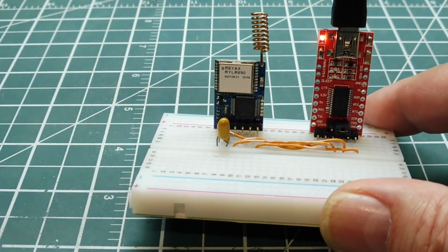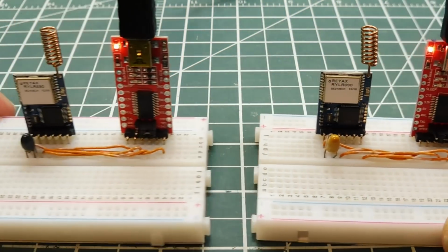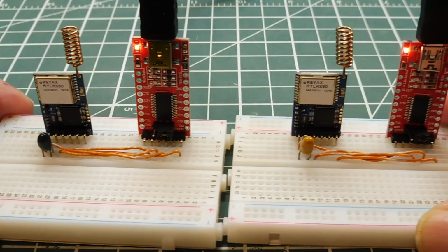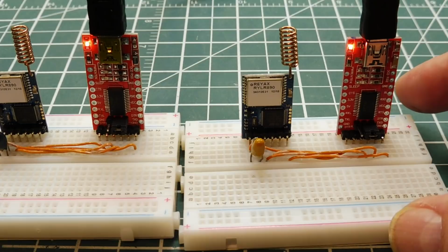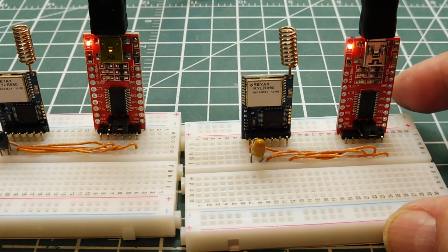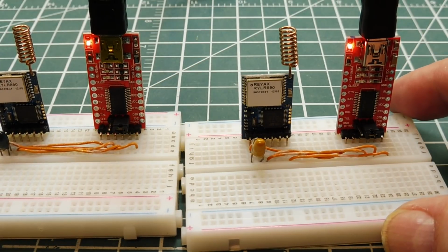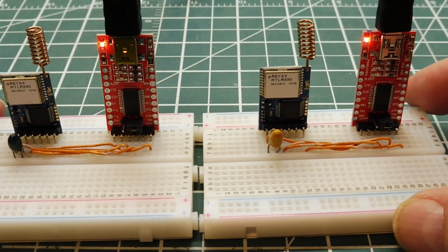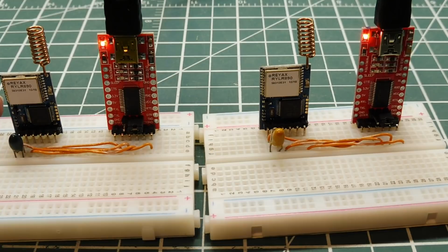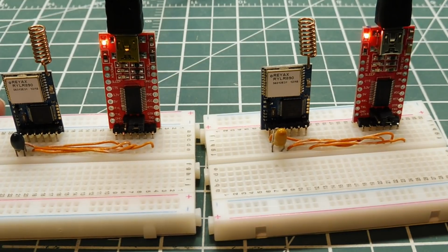I have two of them hooked up, a transmit and a receive, and I'm using a serial terminal program on my transmit called RealTerm, where I can enter the AT send string into a text box and then hit a button and it'll send it all at once with a carriage return and line feed. So I'll send the string hello world, and I have a receiver on.